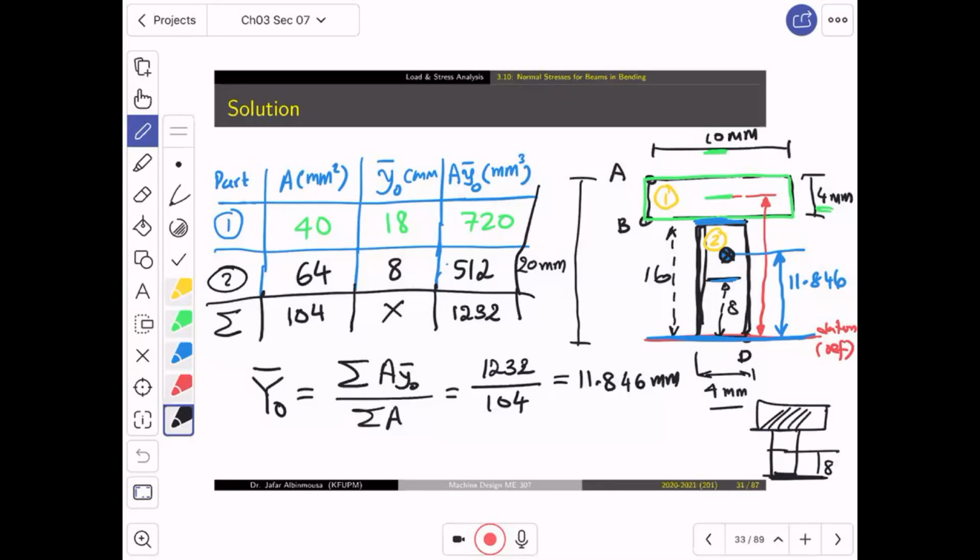Now, what is important is that, yes Ali. If we do it with x bar, will it give the same result or will it differ? How? We did it now with y bar, right? With x bar, it will come out for you, Ali, that the centroid is located here. And we didn't talk about it because it is symmetric, why should I tire myself? I didn't bring you geometry like this, where some of the material is shifted so the centroid might be located somewhere in the middle. No. Most of the time we will deal with symmetric geometry with respect to the x-axis, but with respect to the y, the material is stacked differently, and that's why we will have a shift.